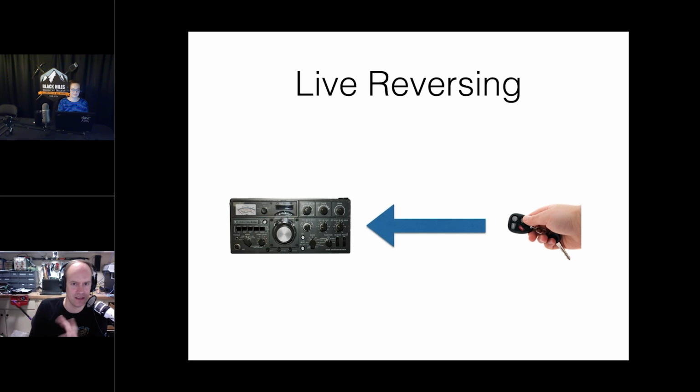And the way I like to talk about it, even though this key fob has absolutely nothing to do with that piece of ham radio gear, is that in the old days, if you were trying to reverse engineer a signal prior to having this capture ability, what you would end up with is somebody generating a signal. Let's say it's just a simple digital signal coming out of this key fob. And then you would have to basically set up all your equipment. You would have to guess, I think it's this type of protocol and this type of frequency and using this type of modulation, and you'd set up all your knobs, so to speak. And then if the transmission came in and you got a successful decode and demodulation, you're like, hey, cool. And if you didn't, well, you had to wait until the target pressed the button again.